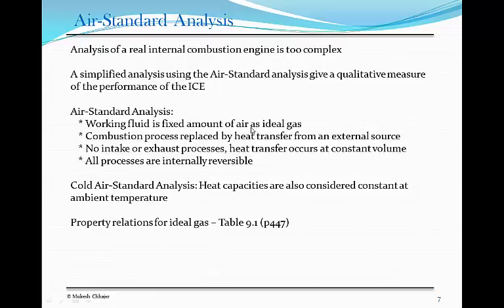So as I said, we can in general have any gas, but just for simplicity, we are going to use air as our gas. So this is called air standard analysis, where the working fluid is air as an ideal gas. We are going to assume that the combustion process is replaced by a heat transfer from an external source. So we don't need to worry about the combustion process, which itself is much more complicated. We can just say, okay, a certain amount of heat has been supplied there. No intake or exhaust process. Heat transfer occurs at constant volume.